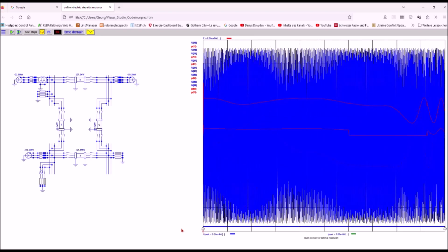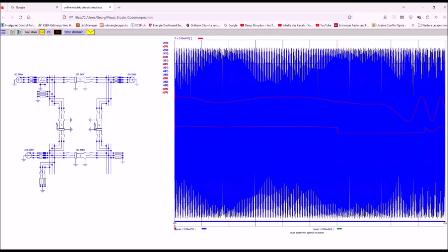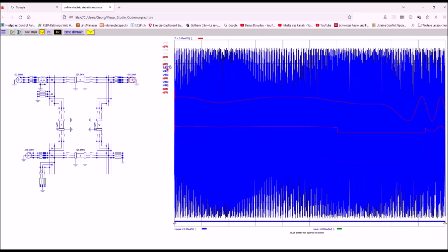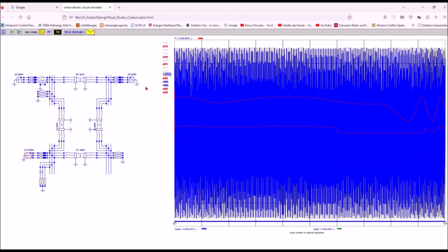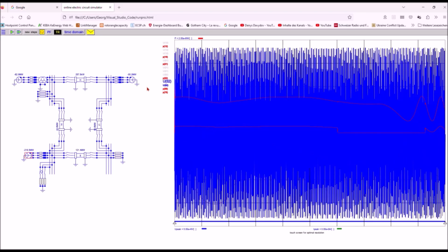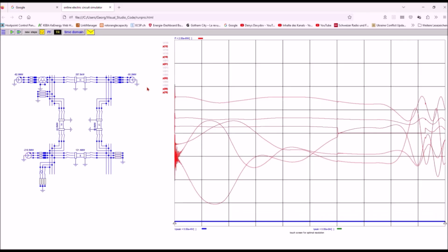I see now the record of all the traces which I had activated in the element input forms. I would like to see the power traces only, and I can hide the traces of no interest by clicking on the list of traces to the left of the record. You see now that with each click on this list I clean up the recorder screen up to the moment where I have only the records of interest on this screen.